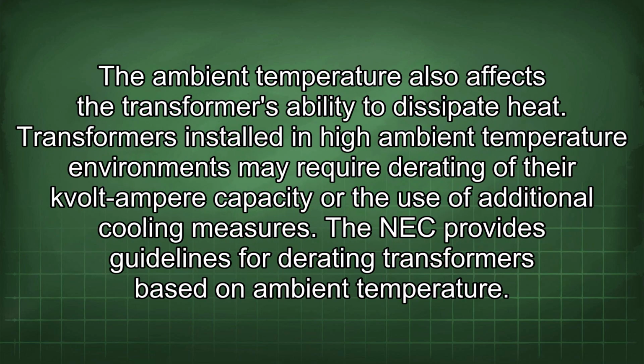The ambient temperature also affects the transformer's ability to dissipate heat. Transformers installed in high ambient temperature environments may require derating of their kVA capacity or the use of additional cooling measures. The NEC provides guidelines for derating transformers based on ambient temperature.